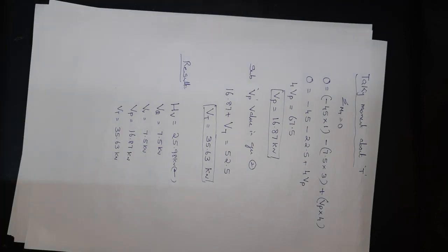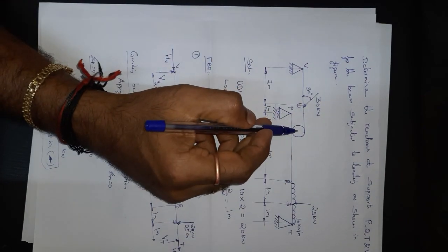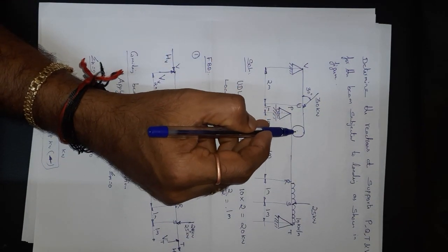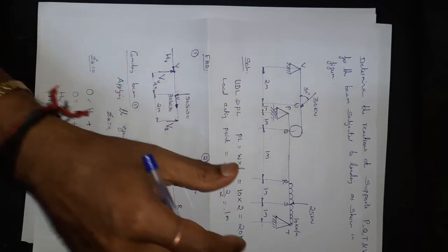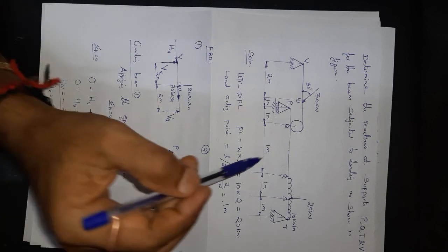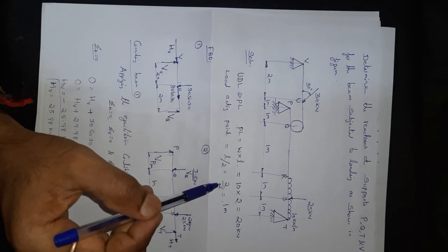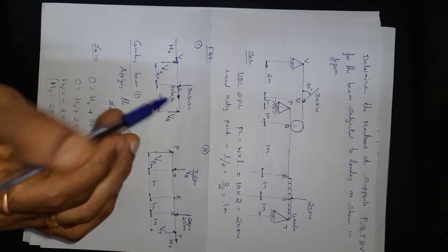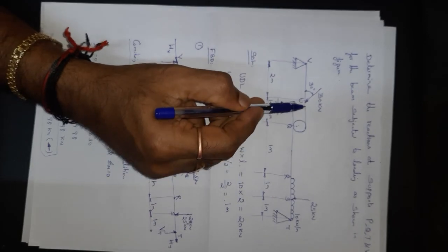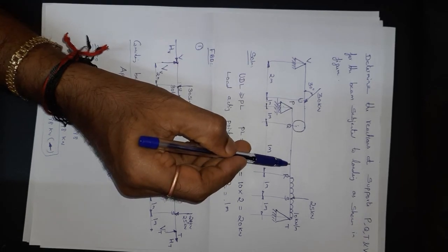Right. When you have such problems, there is a combination of the beam, that is two beams are there and which is supported by, in between the beams there is a support, there is a roller support. Then you'll have to consider this and do two FBDs. First, the UDL or UVL, whatever the loads are there, that needs to be converted into PL. Then you just start drawing the FBD and considering this is FBD for beam 1 and FBD for beam 2.